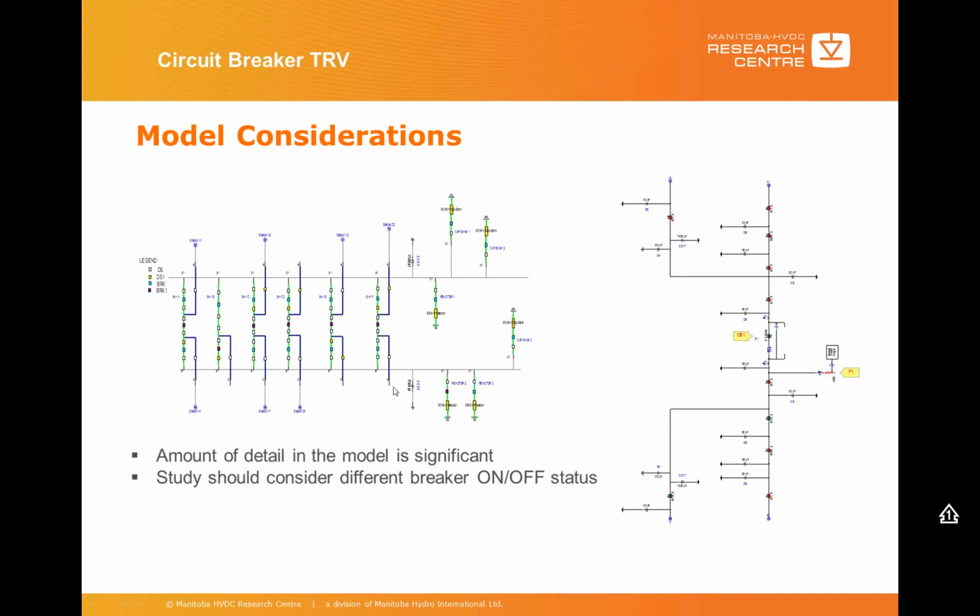That's why you probably need a detailed representation of the station and to place the breakers correctly. Meantime, you have to get some information on how the station is normally operated. Are there any restrictions or operating procedures that should be considered during this study?